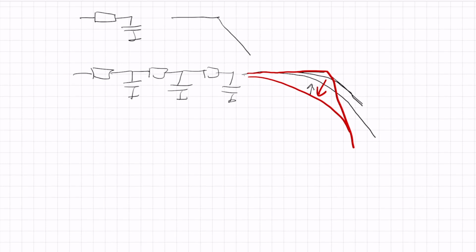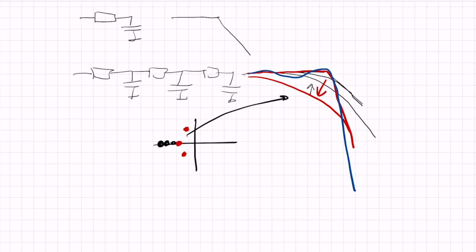And why is that? Well, if I look at the mathematical properties of such a filter, all the poles are on the real axis, and that gives this a round shape. If we want to make a steeper filter, we will have to put the poles more complex. So this is a third order filter where we have 2 complex conjugate poles. They are complex and 1 is real. And if we would make that as a filter, we could make a filter that behaves like this. So normally the steeper it drops, the more ripple you get over here, but you can make better filters. But just with passive resistors and capacitor, that is impossible.